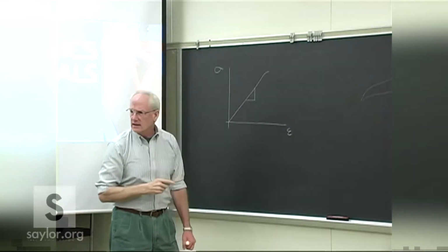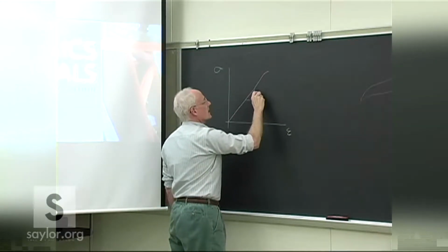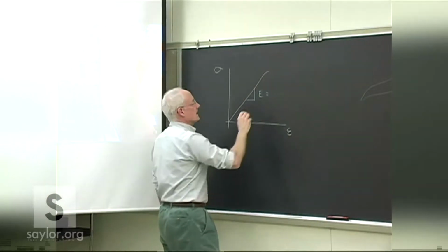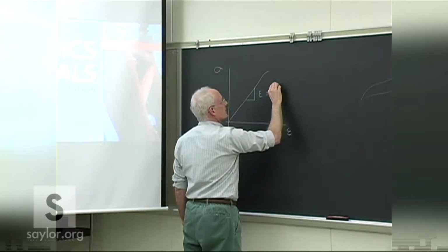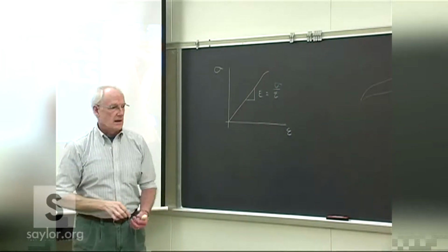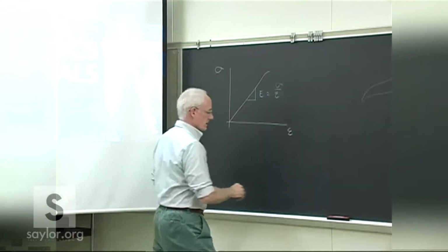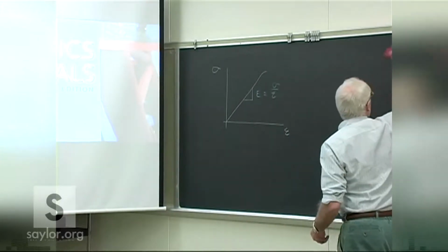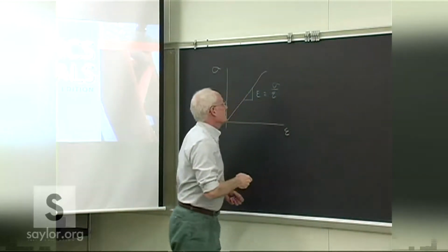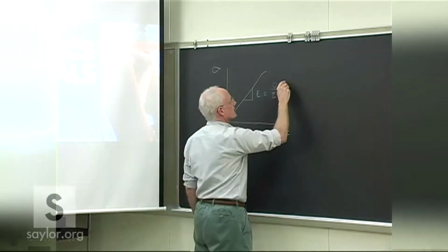It's no different than other types of numbers we have for materials like density. And we call this the elasticity modulus, the modulus of elasticity, however you want to put it. It's the stress over the strain anywhere along that elastic linear region for the material. So we got our first look at that as a material property now, and it includes, of course, the actual deformation of some of the materials.